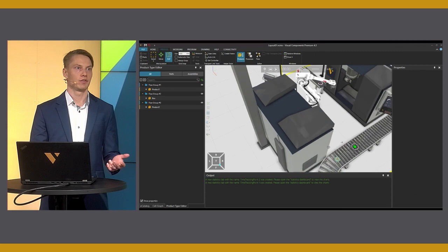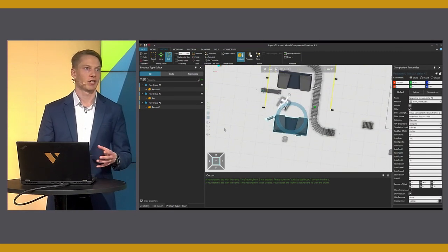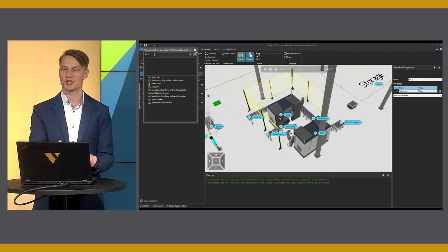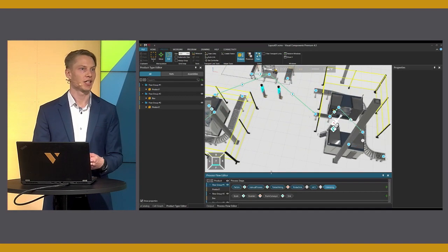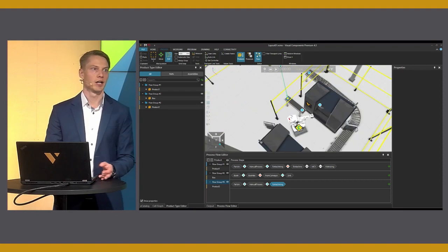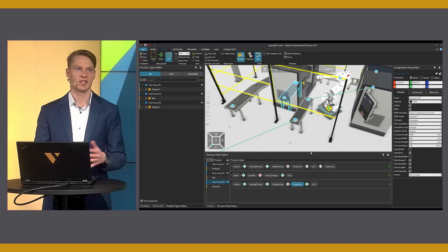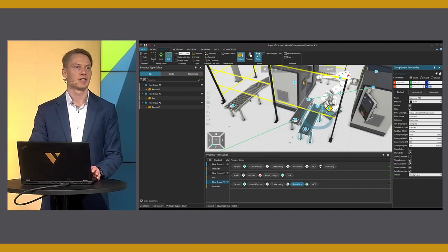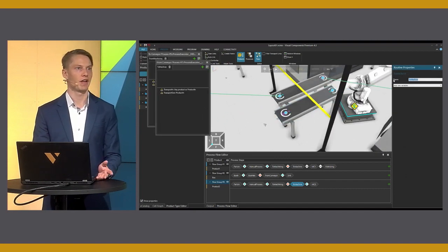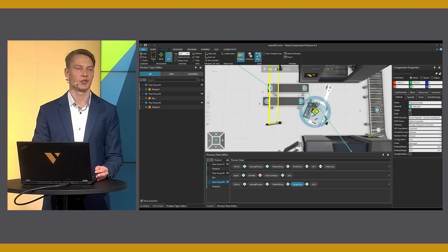We add the new dedicated machine to the other cell for that new product and try to fit the machine in and moving the whole cell in order to utilize the room between the pillars you can see there, defining the machining time and connecting it once again to the flow. So this time the new flow group actually was created since the product is not following the same flow as the first one. The additional processing must be done manually, so we add an additional conveyor there that will bring the machined product back out from the cell for the human operator.